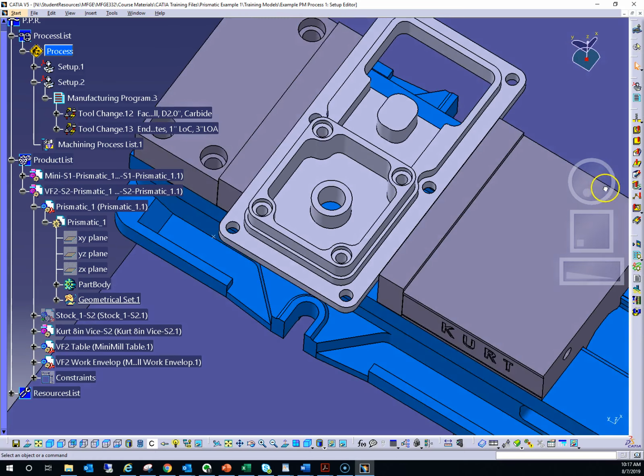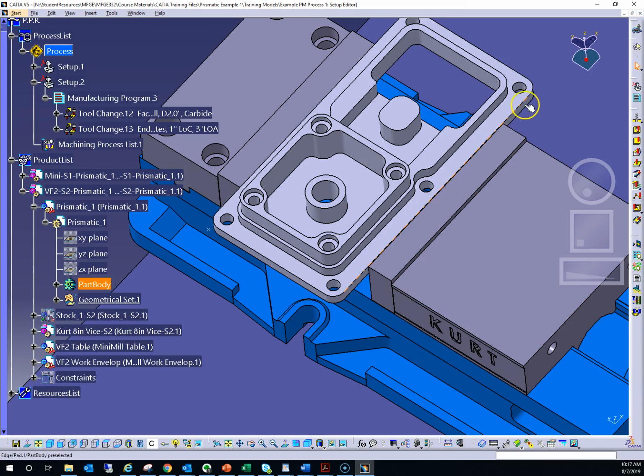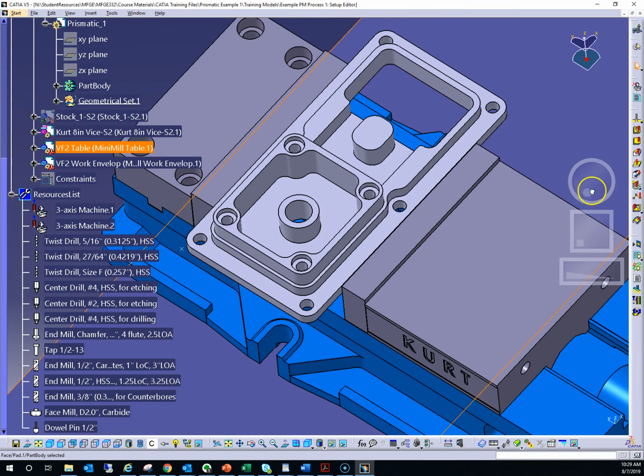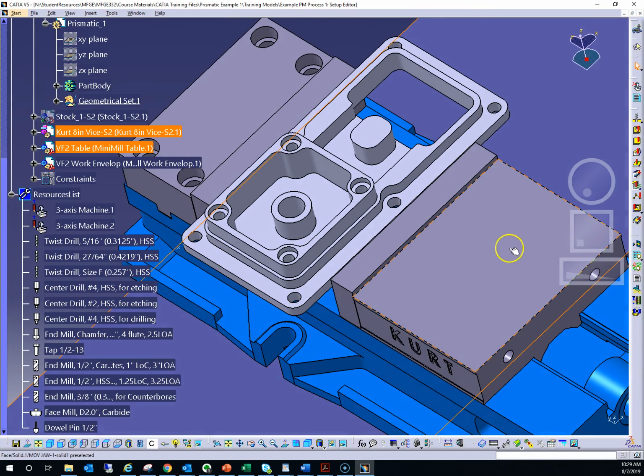If we think about the operations needed now to machine these holes, we of course need to do some center drilling. So there's center drilling of these 6 holes, center drilling of these top 4 holes. There's true drilling. And then there is blind drilling of these holes, counterbore, and then tapping to put the threads on.